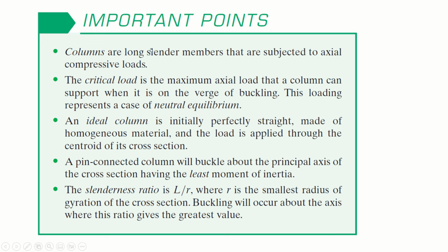Important points: columns are long cylindrical members that are subjected to axial compressive loads. The critical load is the maximum axial load that a column can support when it is on the verge of buckling. It has not started buckling, okay? This loading represents a case of neutral equilibrium. An ideal column is initially perfectly straight, made of homogeneous material, and the load is applied through the centroid of its cross section. A pin connected column will buckle about the principal axis of the cross section having the least moment of inertia, as we already discussed.